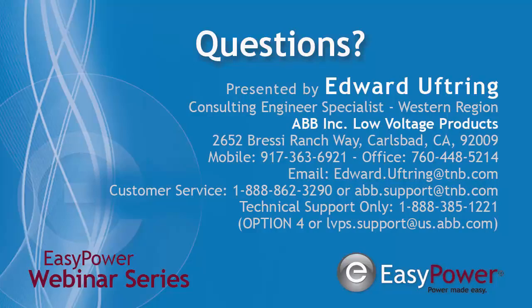In slide 3, showing 3 breakers, instantaneous time looks longer for larger breakers. Is that the case? It all depends on what you set it up for. So a larger breaker can have a quicker time, or it could have a smaller time. The rating of the breaker is not actually indicative of the time delays or the curves that are being shown. What those curves depend on is the trip unit, which are either dip switches or electronic trip units.